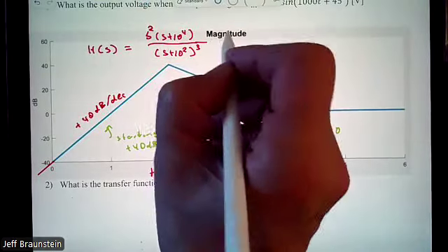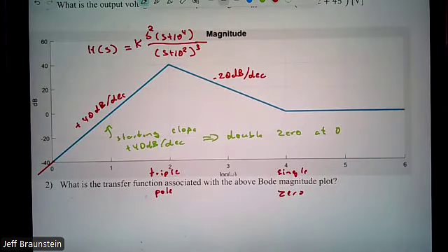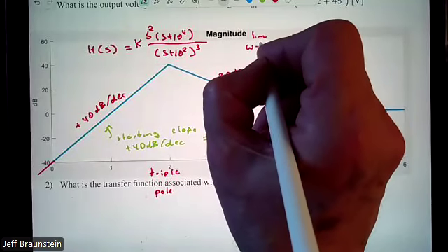We've got enough, but there is something that's missing, and that's a K term. There could be a constant term that we haven't paid attention to. Poles and zeros only give us our parentheses and our S squared in the numerator. It doesn't tell us what the constant would be in our equation. How do we look at that constant? What is the dB value in the limit as omega goes to infinity?